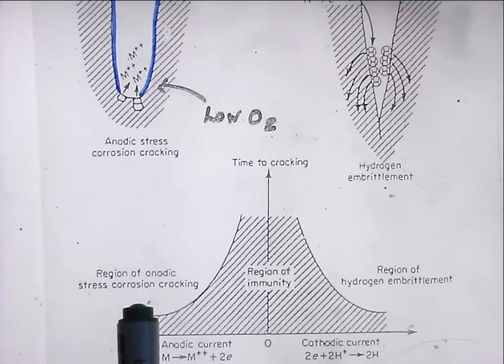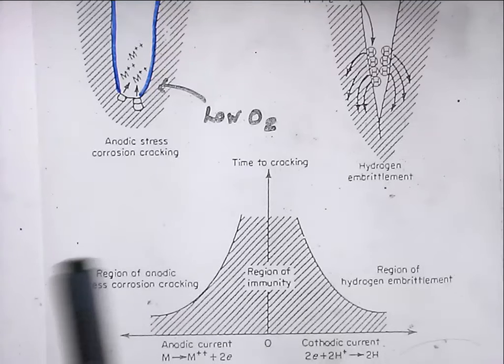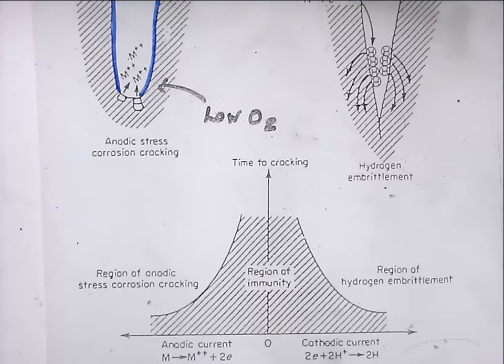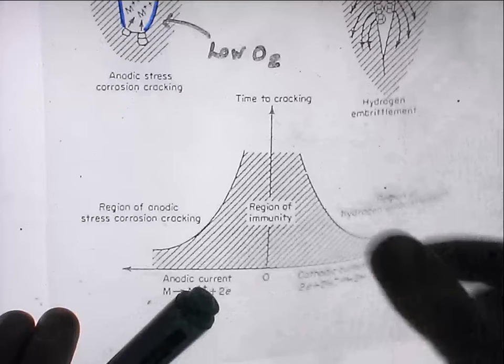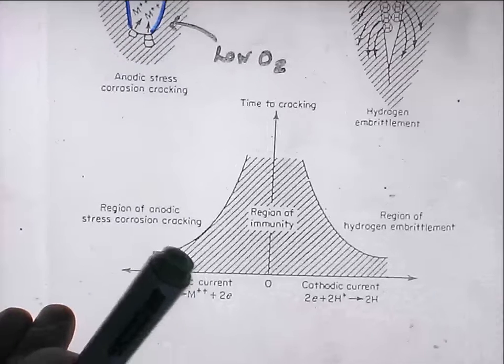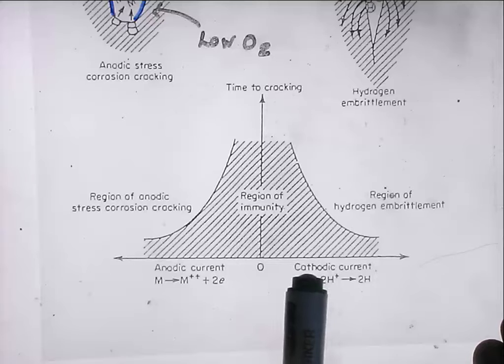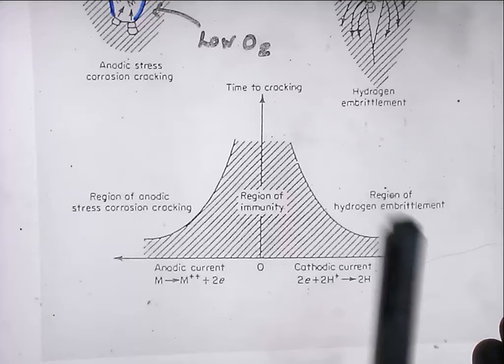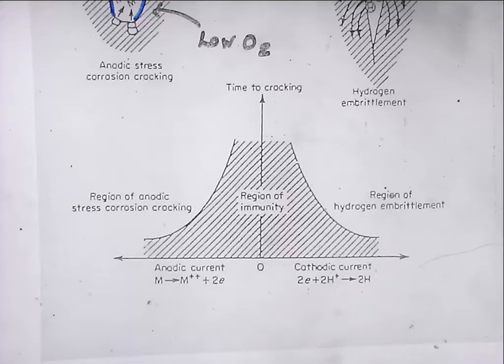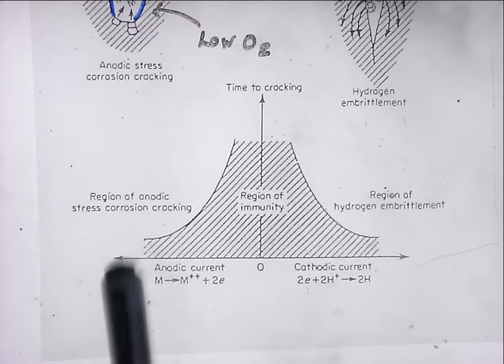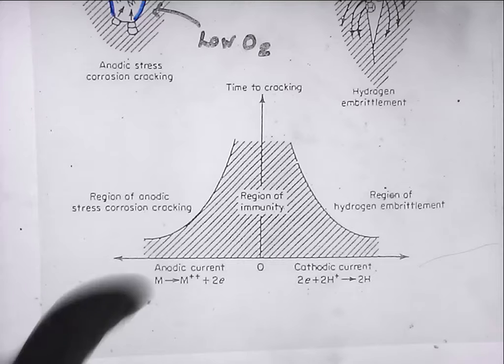Well, I'll show you a couple of samples. These are actually scaled down compact tension specimens. These ones are actually of a weld, what they call a transition weld between two different types of material. There's a notch put into them, and then there are loading bars put into the top and bottom, so you can pull the block open. It's been exposed to a corrosive environment, an environment which causes stress corrosion cracking. And the interest was where do the failures occur and what happens.